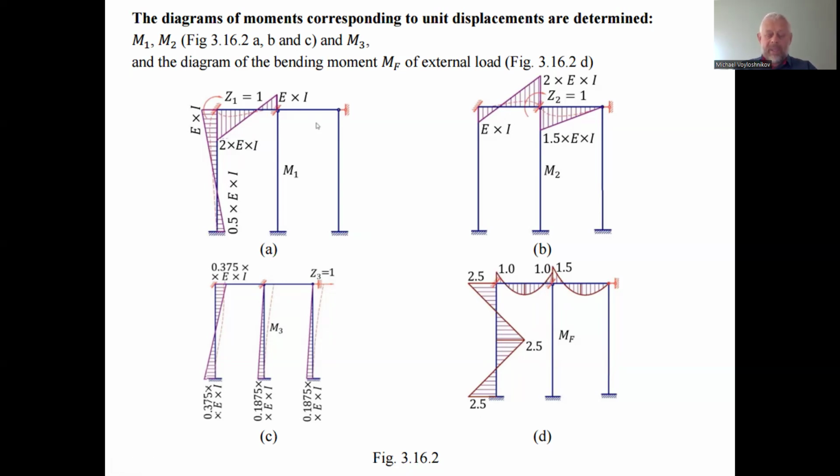And when we have the correctly found bending moment diagram with signs understandable for us, we can find the signs of the transverse forces diagram, as we remember that the transverse force diagram is in a derivative relation to the bending moment. The bending moment diagram is an integral function of the transverse force diagram, and the transverse force is the derivative of the bending moment.